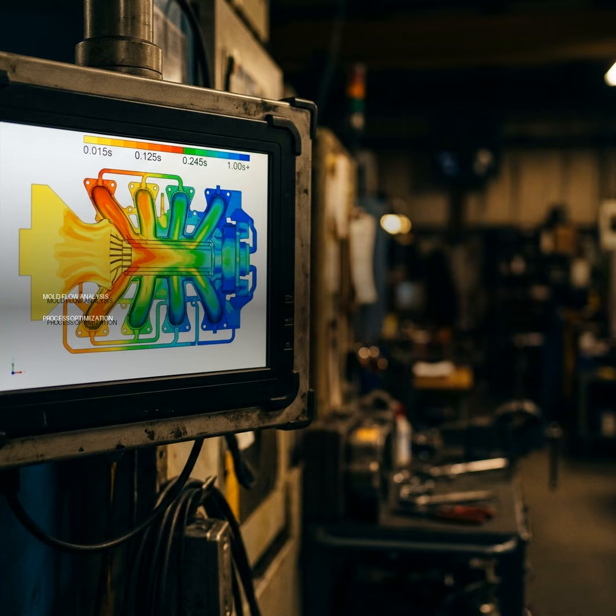So, how does someone actually do a mold flow analysis? What's the basic process you'd follow? Well, it starts with the geometry first. You've got to generate a mesh from the 3D CAD file, usually an IGES or STEP file, that kind of thing. Note mesh quality is super important here. It needs to meet the analysis requirements. Too thick, you get inaccurate results. Too thin, and the computation time goes through the roof. It's a balance. Right, so you're preparing the digital model.